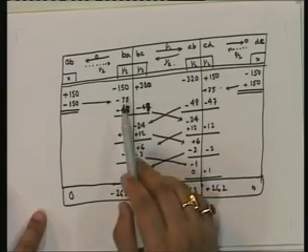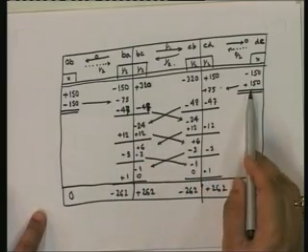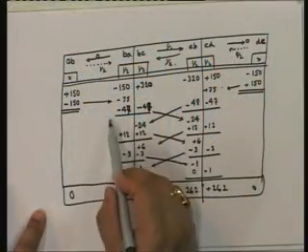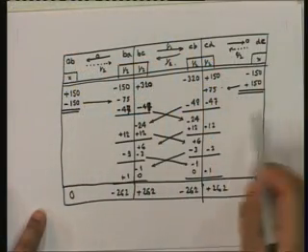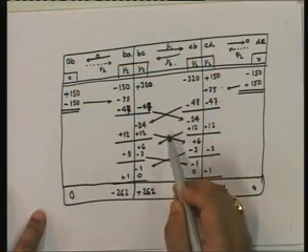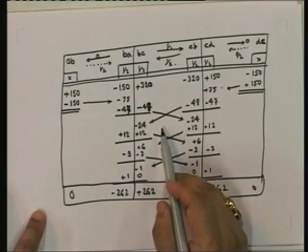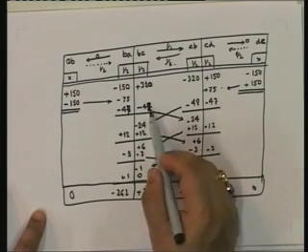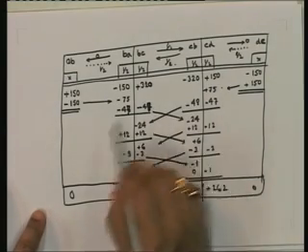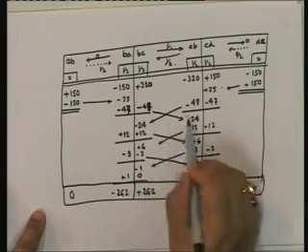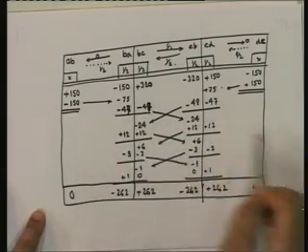So, in other words, however many continuous joints we have, we look at their distribution of the unbalanced forces at one shot. So, we do all the distributions at one shot. You will see this, if there are more members, all would be distributed. Then the next phase is the carryover phase. So, you carry over everything that you have to. In this particular case, only the carryover is here because there is no carryover on the other side.